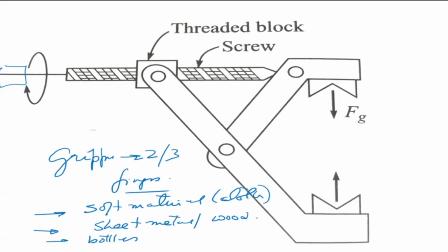So if you're trying to pack bottles, or cold drink bottles like Coke bottles, what is required is that it should be able to pack as many bottles in one crate as it can in one shot. If you're using a 2-finger gripper, it catches one bottle, puts it there, takes one more bottle, puts it there. That will take a lot of time. Whereas if you can have a gripper which takes maybe 24 bottles in one shot and puts them there, then that is better. So these are some of the examples where 2-finger grippers would find it very difficult.